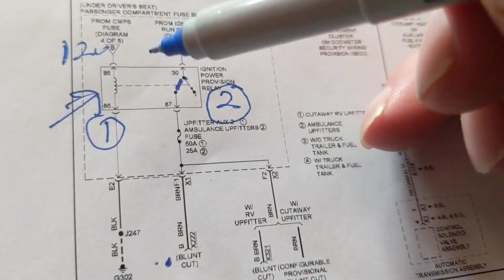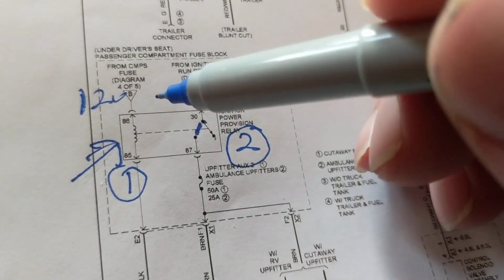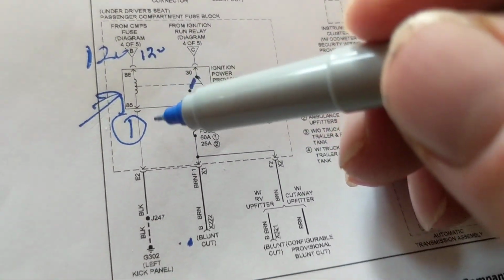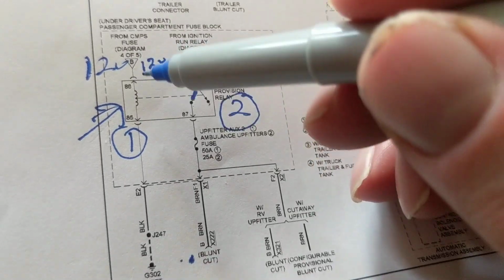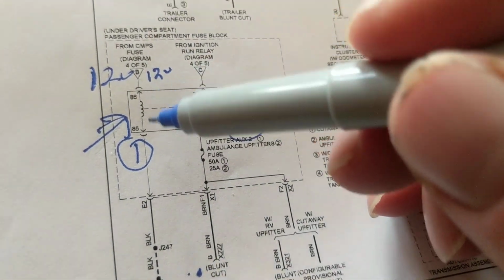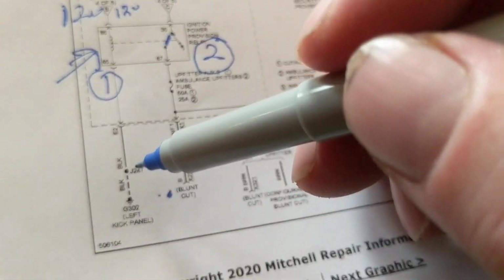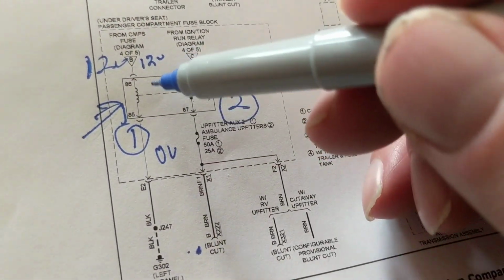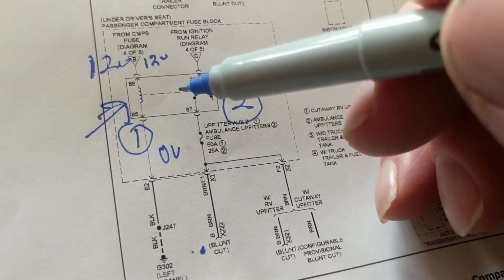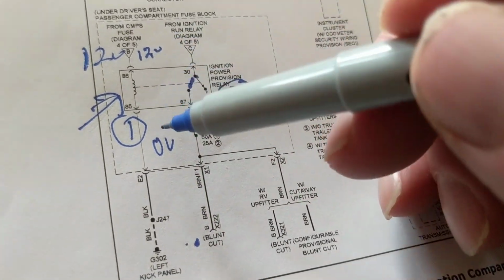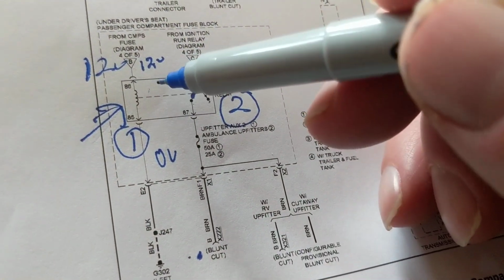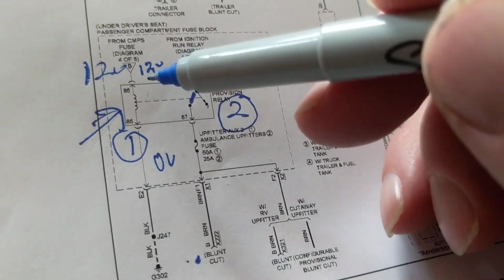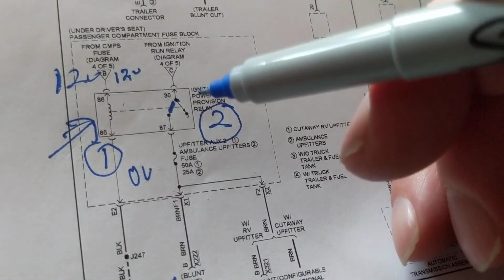So if you understand the current path, let's understand the voltage. I have 12 volts over here. How much should I have over here? If current is flowing through this, I should have a voltage drop across this. Since this is connected to ground, I should have 0 volts here. How much is the whole voltage drop? 12 volts across here. 12 here, we have 0 here. That means we lost it somewhere. We lost it across the coil. Fine. This tells us this is operating.